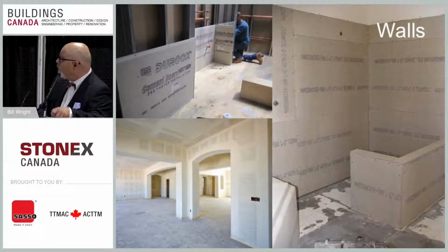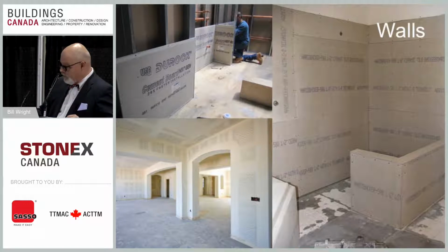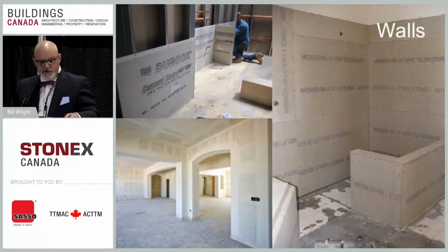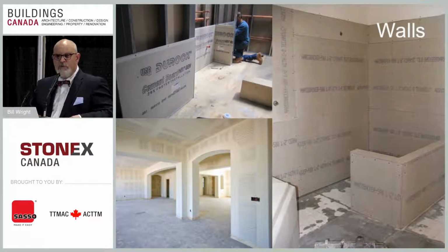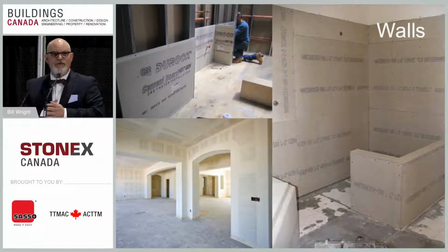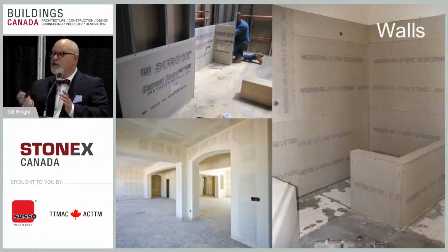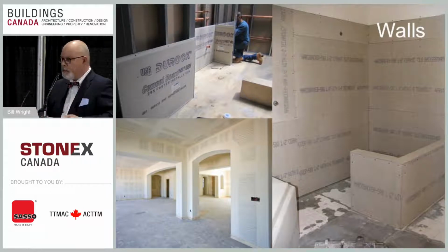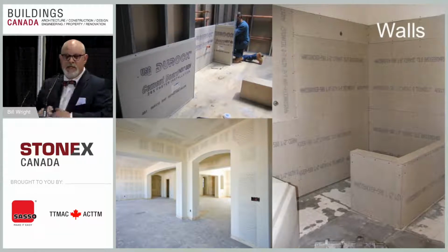Walls, the same thing. Like I said, we like cement or cement-based type products for walls. Otherwise, we like parging. Recently, I was called to a job. We'd supplied some limestone, a little bit of a moisture-sensitive stone, and the phone call came that they had these big wet circles coming out on the stone. You can imagine that, the contractor decided not to prep the wall properly and blobbed the mortar on the back of the stone, and it was bleeding through.